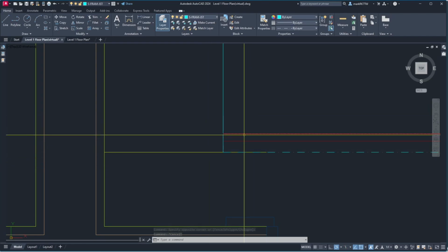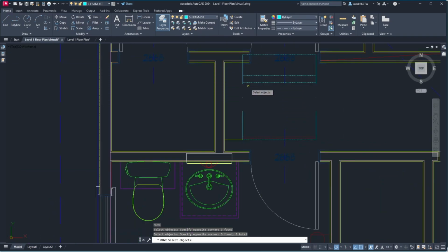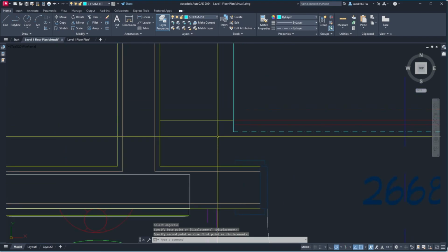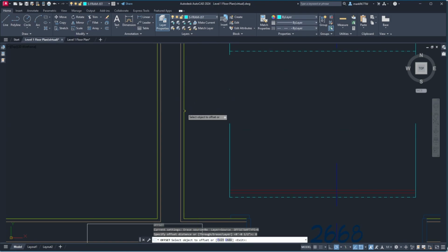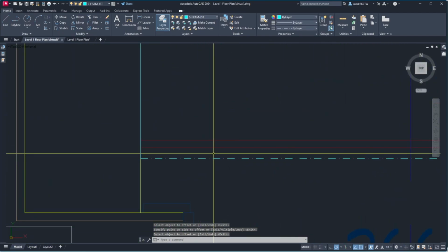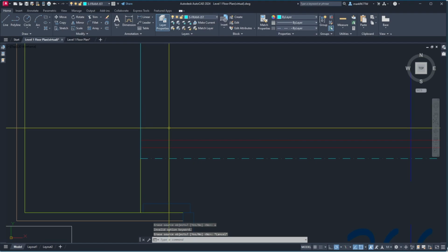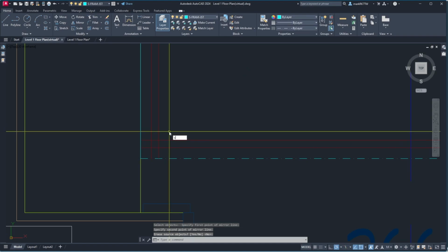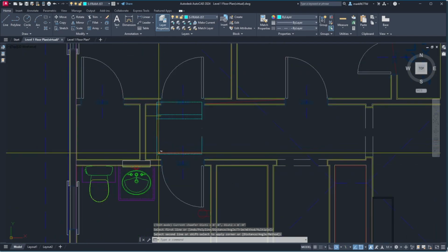Now this line is to that line. So this whole system moves from here to here. And then off of this line was 8. And then off of here it was 8. Now, what I want to do is I want to mirror this around this corner. Again. Come out 45. Boom, got it. Now I could chamfer this if I want to clean it up. I don't have to. These are my junk layers, so they're for my information.